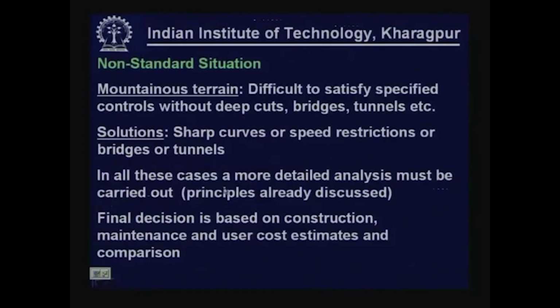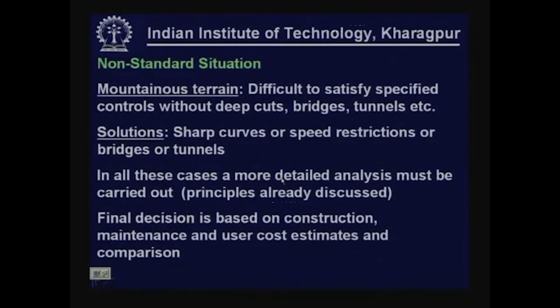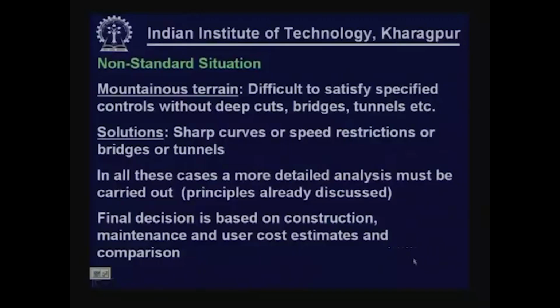And in all these cases, more detailed analysis must be carried out, and the procedure I have already discussed. And the final decision is based on construction, maintenance and user cost estimate and comparison. So, again the final decision must be made based on life cycle cost analysis and comparison. Take all the cases, one with this, one without bridge and all such possibilities, and then make the final decision based on life cycle cost analysis, considering construction, maintenance and user cost estimates.